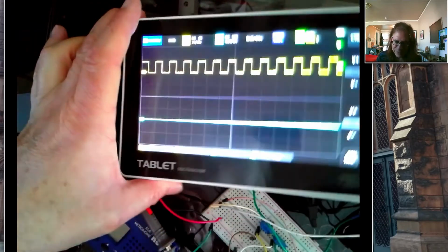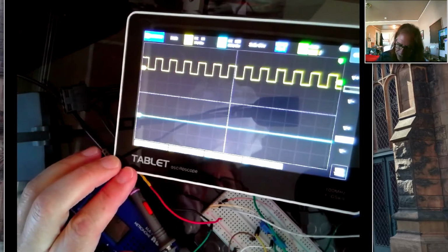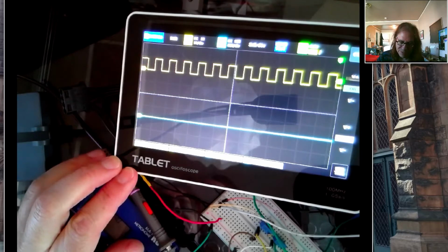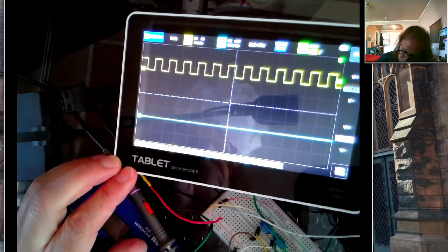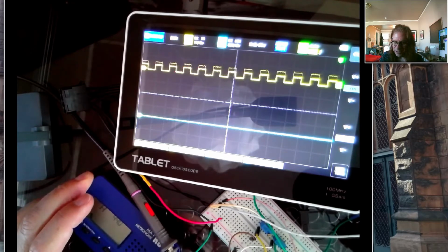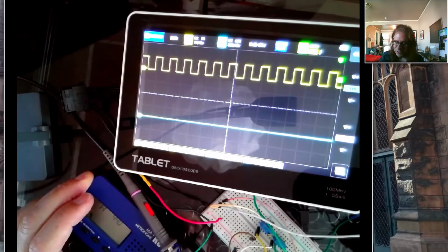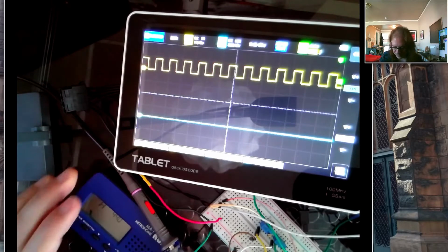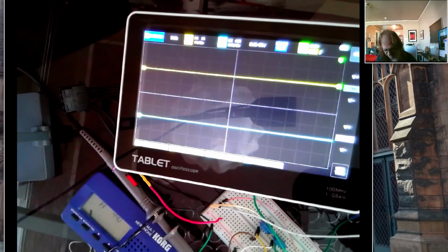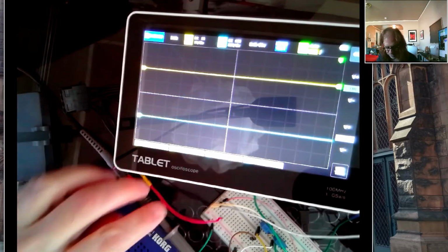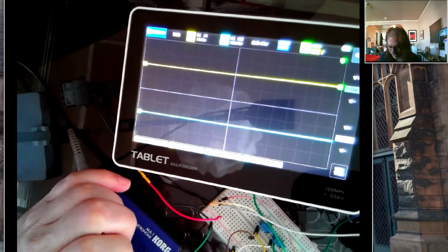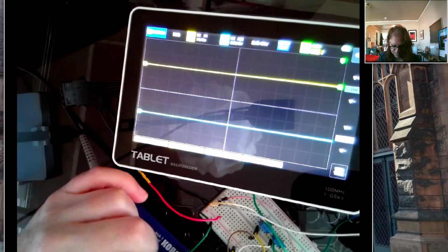It says 440, you can't see that. But this line right here is 0, and so it's going from 0 volts positive. And this is 1 volt per division, so it's going up just about 1 volt. And I can change the amplitude of that by using the volume knob. But 1 volt. So this is just a pure test input signal. So let me go ahead and connect that tone generator to the input of my circuit, and let me hook up my scope probe on the output of the circuit coming from pin 1.